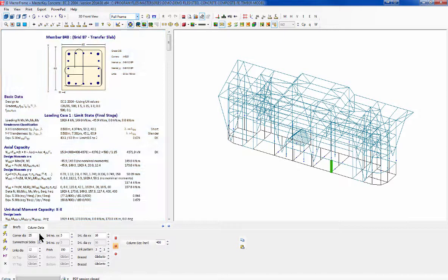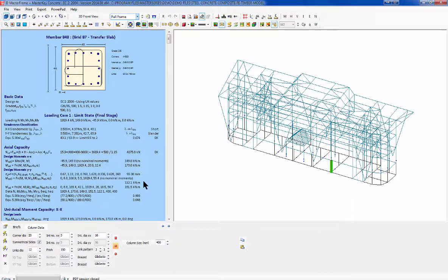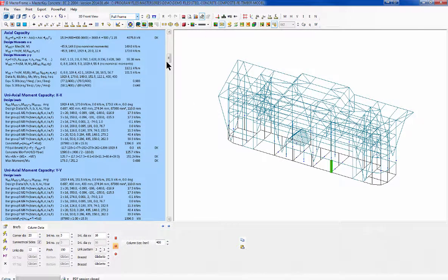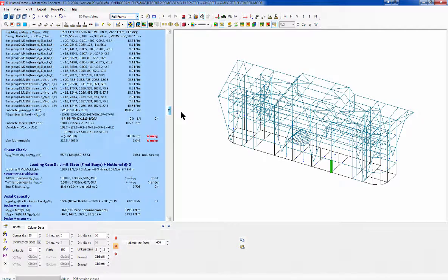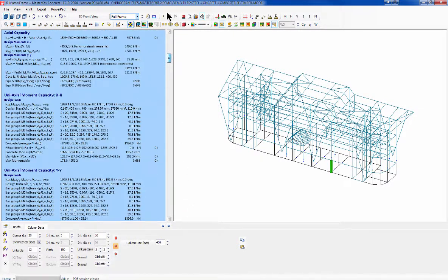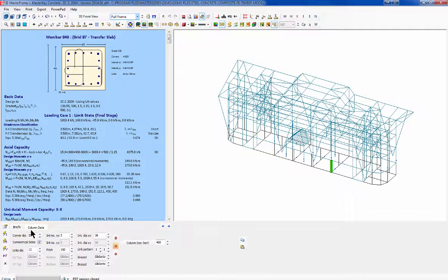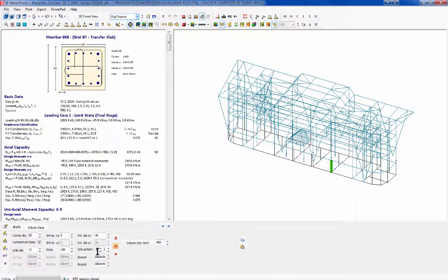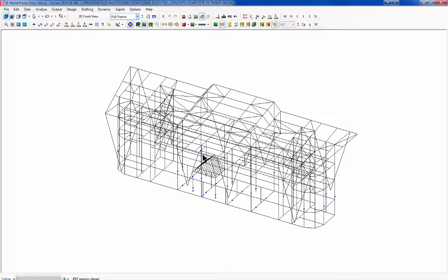The design is very straightforward, and you can ask it to go and design it itself. And it has attempted to design it, and what's it decided to ignore? It's very low overstressing on that, and it's decided, do you want to go that stage further, or are you happy? In my case, I'm going to say 25s. So we can design our beams, we can design our columns, everything in here. Now the flat slab area I will quickly look at the very end if I have time. So that's the concrete. Steel, concrete, what's next?